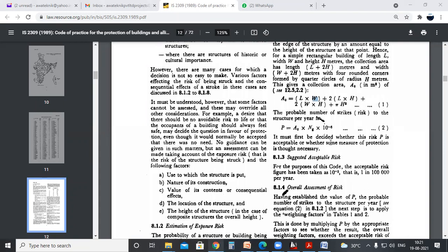Ng is 7. That we have taken from the annual thunderstorm days, right? From the annual thunderstorm days, we have taken the location as Cochin. So the annual thunderstorm days number was 63. So the mean value we have taken, from the table we got the value as 80. The nearby value is 80. From that we have taken the mean value.